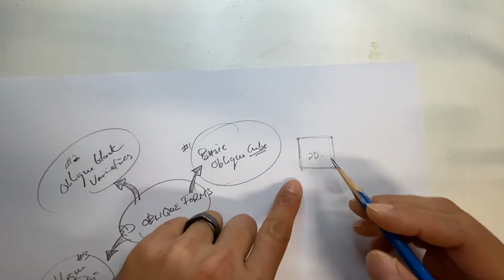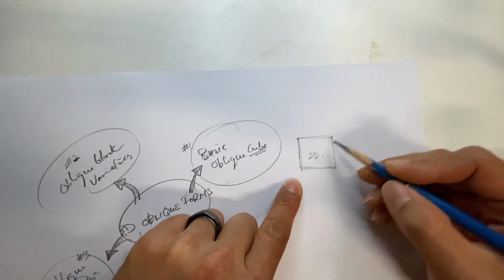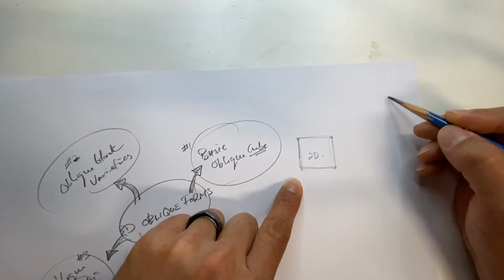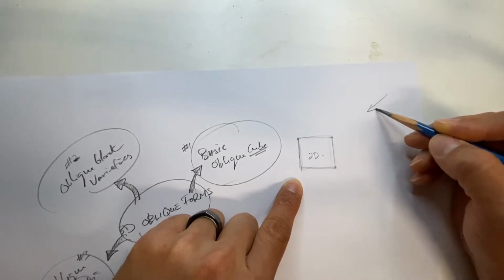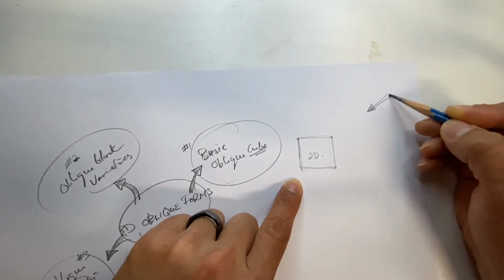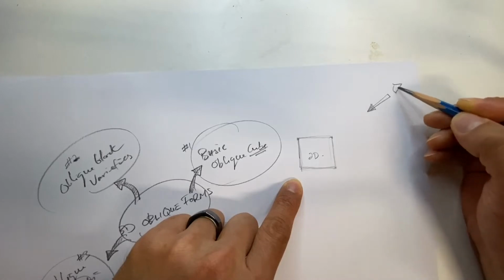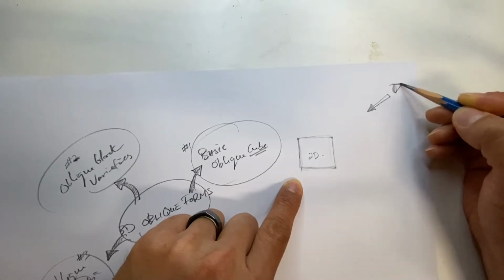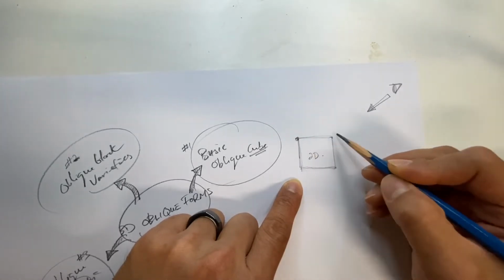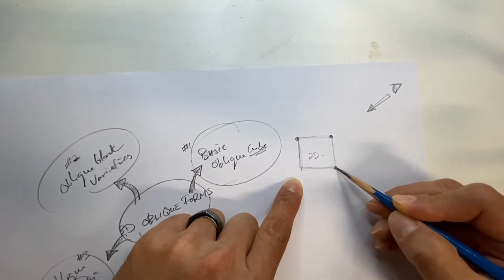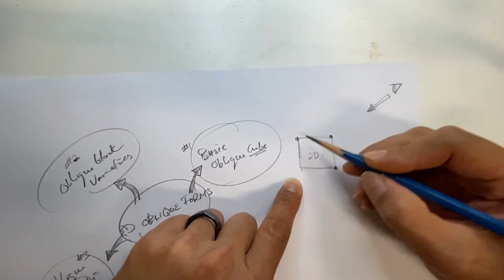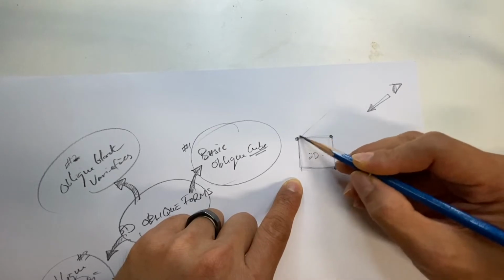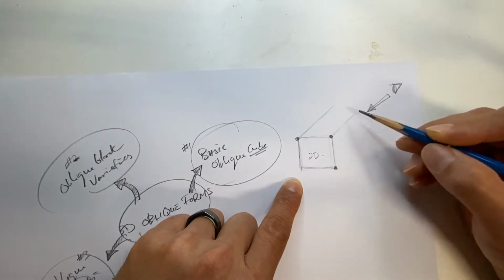In this case, imagine you were to look at this object from the right. Look at this 3D object from the right, then you pick the 3 edges that you can see from the right hand side, and you project the lines to the horizontal at 45 degrees.